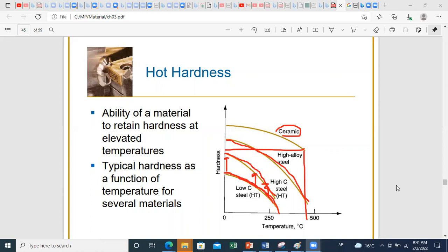The idea, look, is that not every manufacturing process will require that you go to very large tension values. Not every deformation requires going to the plastic region in a tensile test, because it depends on the stresses that you are undergoing in the deformation. So if you have a test with very large shear values, not going to very large tensile stresses, you have the option of ceramic because it will allow you to keep large hardness.